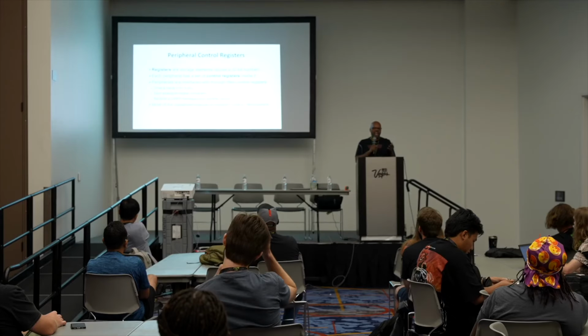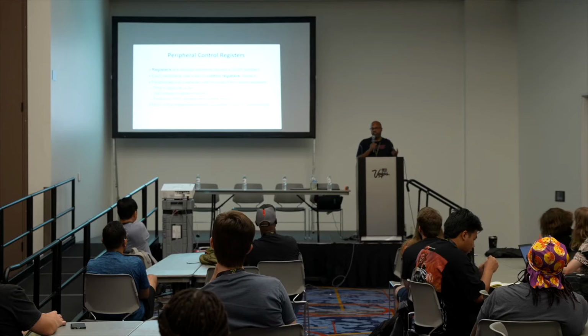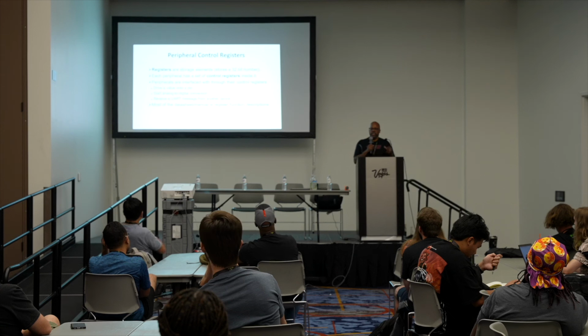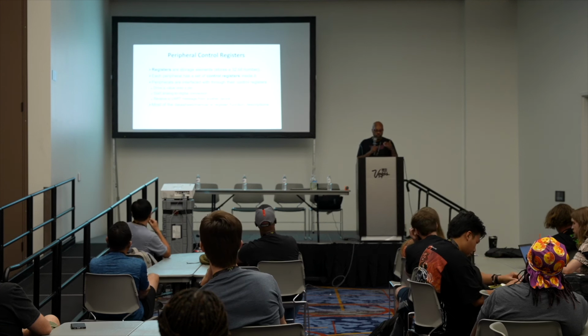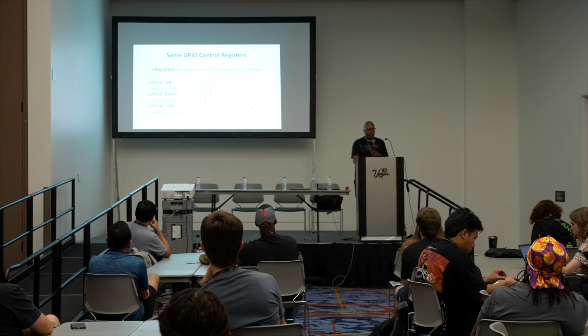Okay, so a lot of my students get sick of this because you're looking at all these tedious details. Oh, I see, it's bit 5 of this register that makes this start, and bit 6 puts it in this mode, and all this. That's why the data sheet is like 1,700 pages long. So that's how you control them, through these registers, whether you want to drive a value onto a pin, or do A to D conversion, or UART, or whatever.